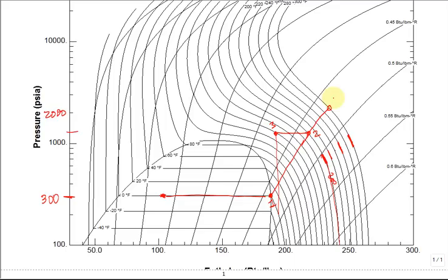Let's say it goes all the way to 300 degrees F. Do you wanna touch that outlet to the compressor? No, you don't. Okay. Now the high pressure is, let's say, above 2,000, right? And now we're going to cool it by 20 degree increments, and we're going to be able to cool it until we get to that same temperature as the previous state 3, right? So that temperature was what, 140? Now if you can cool it such that it's 120, that's even better.